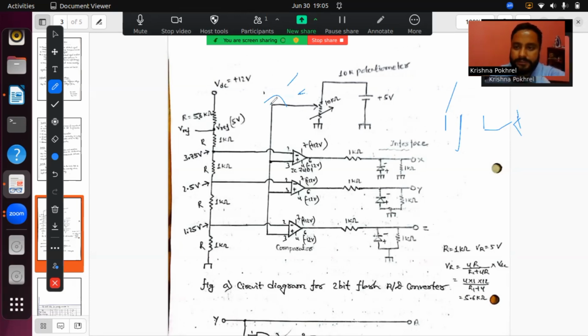Now this potentiometer will be connected to the 3 number terminal of each and every op-amp, and this helps to compare. It is a comparator actually. What type of voltage are we getting here? We are getting 3.75 volt. And here, if we get a value less than 3.75 volt, then what happens? Let me see that and explain it to you once.